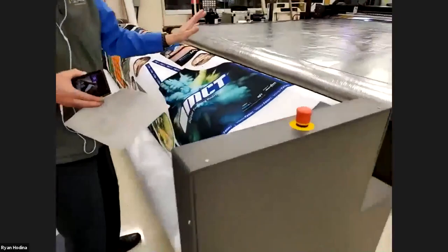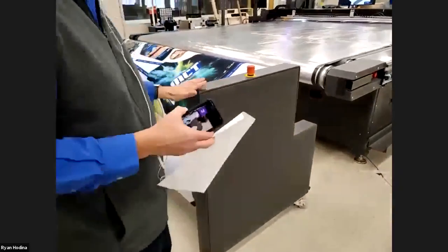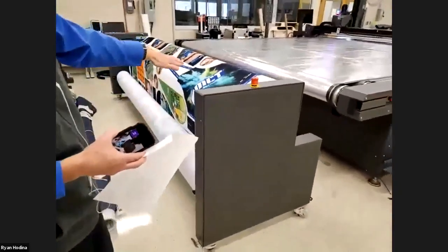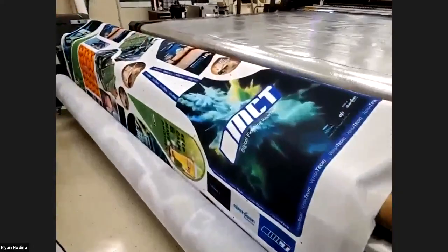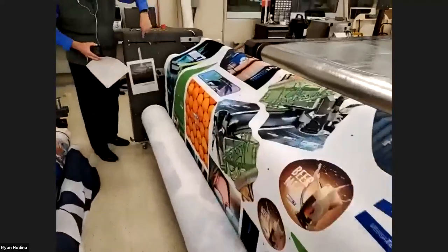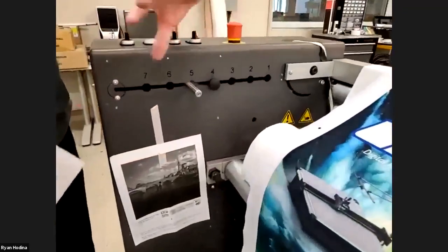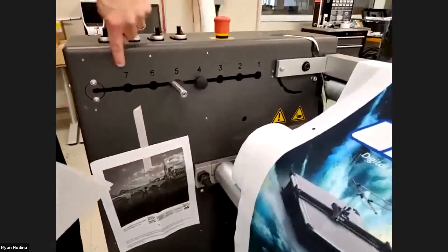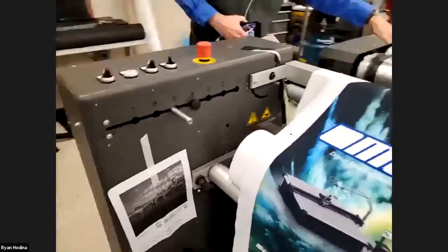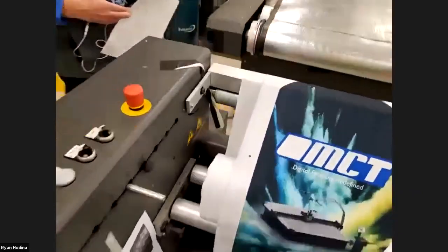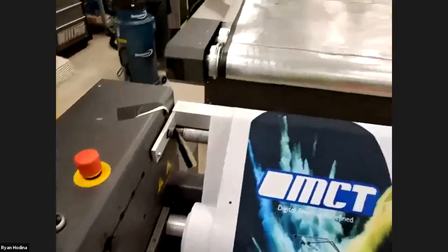This is an optional item we use for folks that are doing high volume flexible goods. This is an automated roll feeder. And with this, you've got several tension adjustments here. You've got a dancer bar, so you can keep your material nice and taut. You can adjust the setting, so it's going to go through exactly what you want it to. Put it on the conveyor, turn the vacuum on, and that'll advance the material, and you can cut very, very high volumes of flexible, soft materials that way.